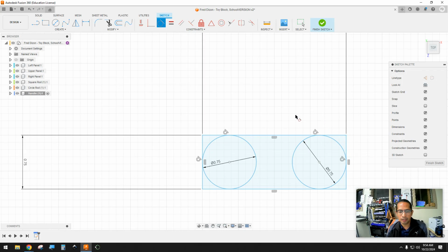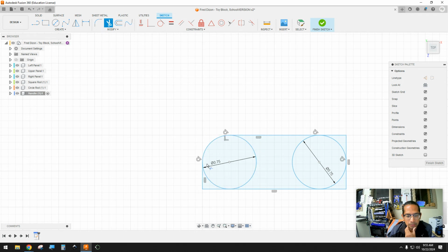Alright, so it's going to be a simple formation. It's just that one circle is going to extrude towards you, and then the other circle will extrude the other way. Let's remove all of these extra corners. The way to do that is trim. Just know that it trims from point to point. So the ending points are here and here. That's highlighted, and this is going to trim that off. Click on those and remove those.